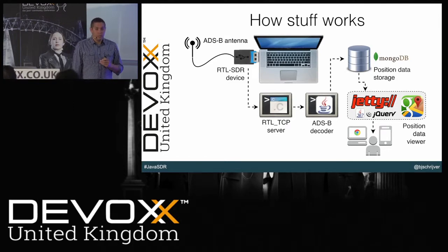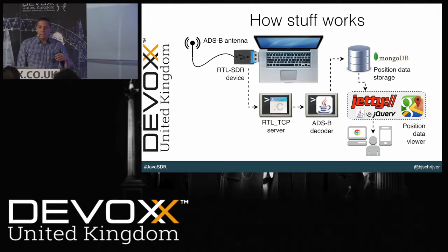1.09 gigahertz. And there are all kinds of plans online on how you can build antennas for this. So I built a small antenna with antenna poles that are tuned to, I think, a quarter of the wavelength of 1.09 gigahertz. I have no idea how to calculate this, but you can just look it up online and then do it. This connects to the RTL SDR device.